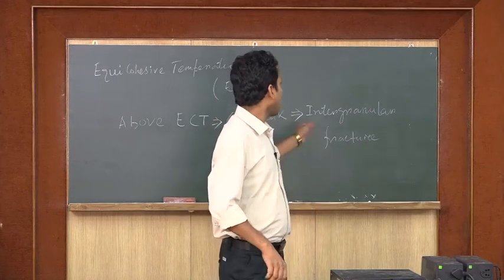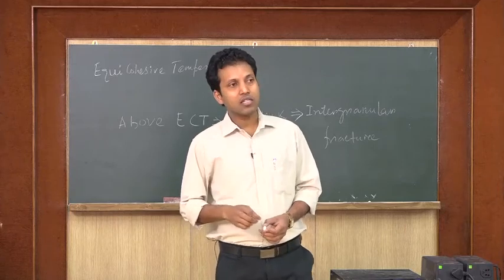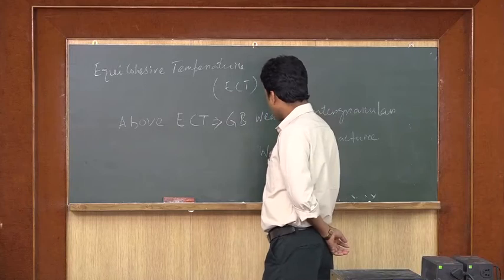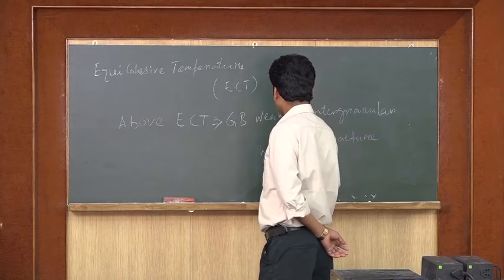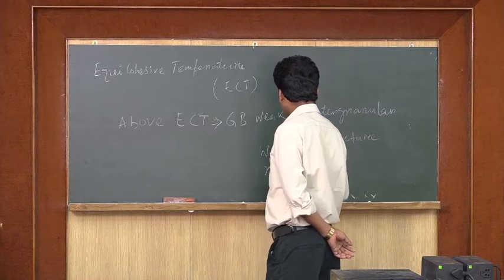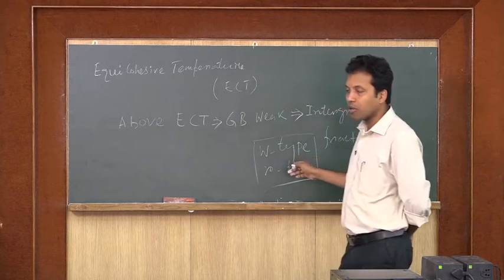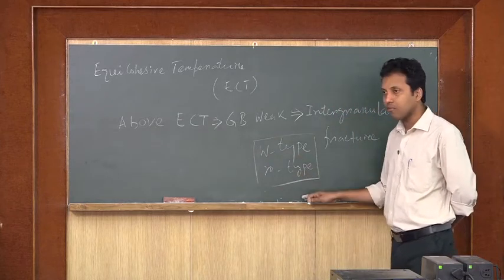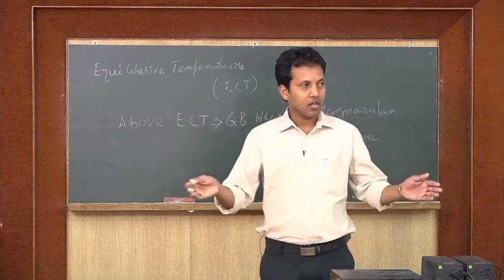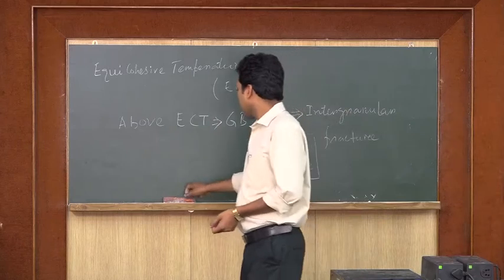So, we have the intergranular type of fracture and different fracture nomenclatures are there. Please open Dieter's book, you can see the W type fracture, intergranular fracture types of creep deformation. A W type fracture, wedge shaped fracture or R type fracture, these things we can see on the material's fracture surfaces. So, you can understand from there.